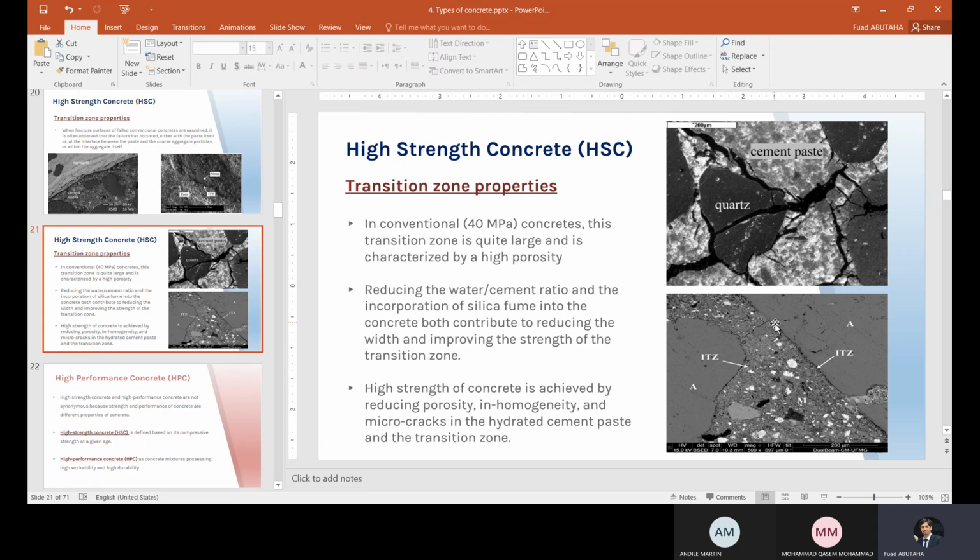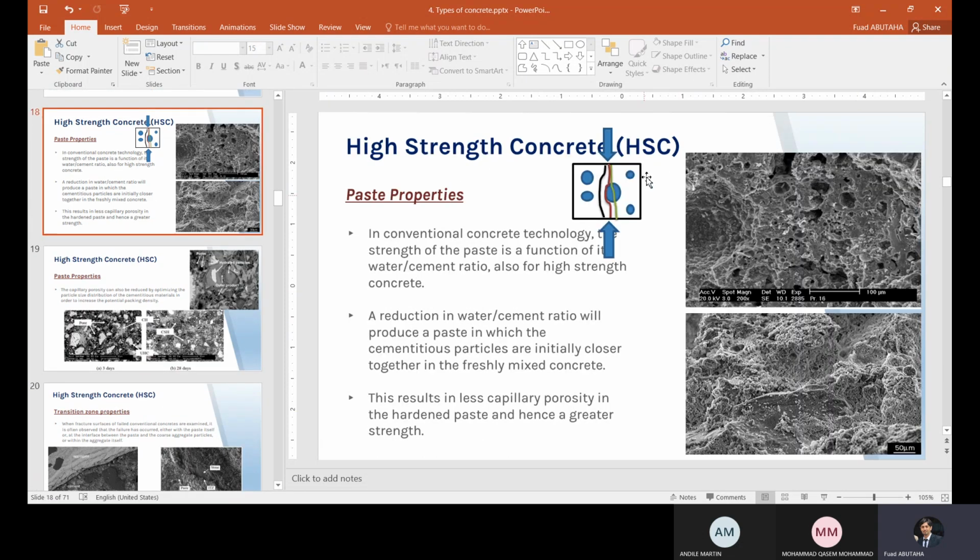Here you can see it is compacted, with no voids between the particles, where A is the gravel particles, or the coarse aggregate particles. With the cement paste here, there is a good bond between both of them, and the good bond prevents the failure from coming through it. So in total, after we understand the 3 failure scenarios, we need to take care of all of them.